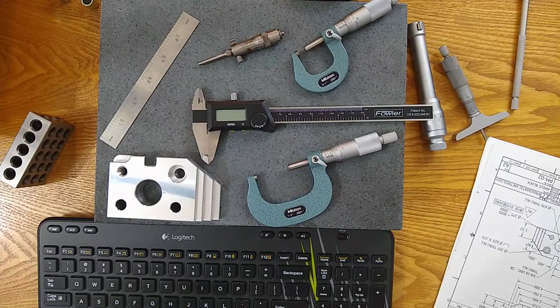Well, generally speaking, a 10-to-1 ratio. If your accuracy is small, it needs to be smaller than your tolerance zone, ideally a 10-to-1 ratio. And in many cases, we settle for 4-to-1 or 3-to-1 because of manufacturing purposes.